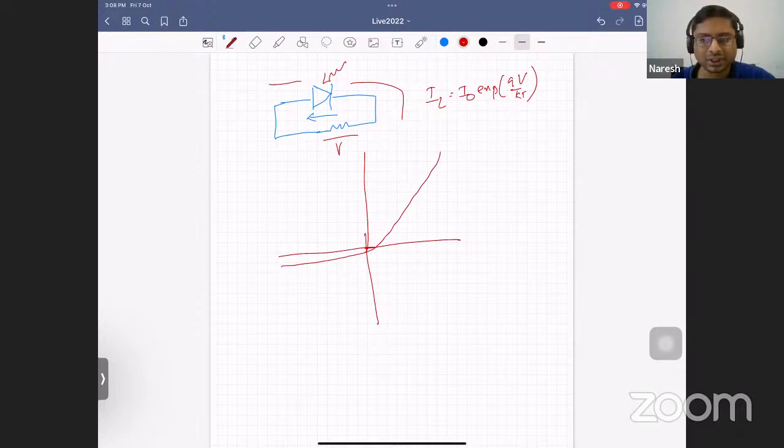Is it possible to use a current to voltage converter as a non-inverting amplifier? No, just the converter will not work because you need to have gain as well, right? We'll have to create an additional circuit, and we can design circuits which can work as non-inverting amplifiers. But then you see a lot of you use op amps.